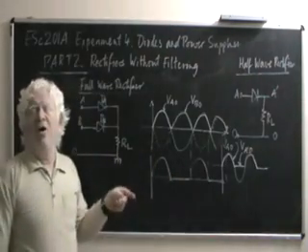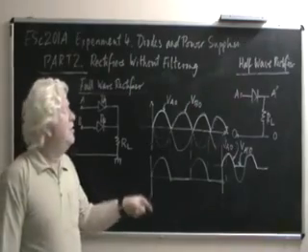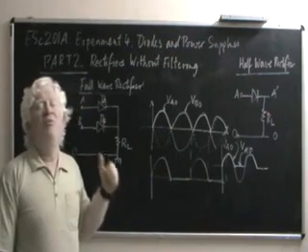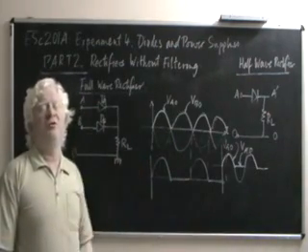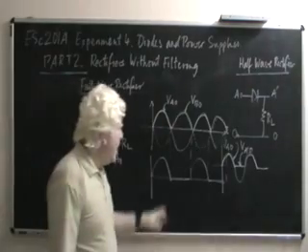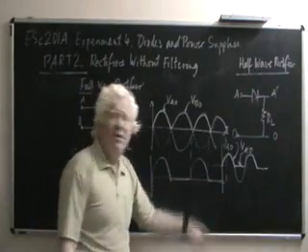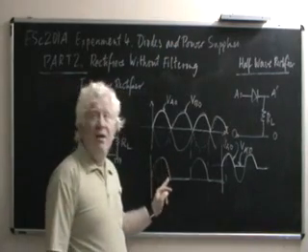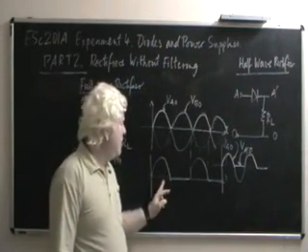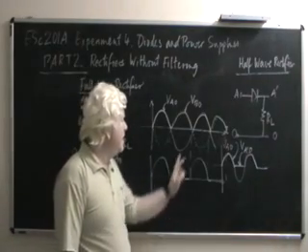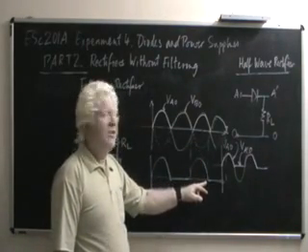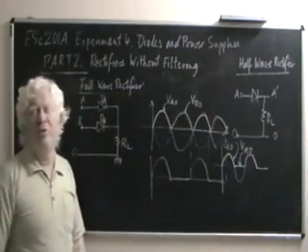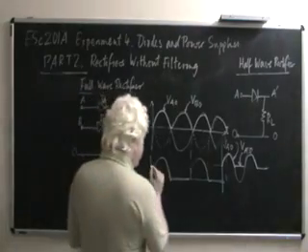We now speak of having achieved unidirectionality of the output voltage. We now speak of how to make this voltage as constant as possible. Clearly, the half wave rectifier looks extremely fickle. Sometimes it produces a large voltage which is along the lines of a sinusoid. At other times it is just zero. Again it's a half sinusoid, then again zero. Not at all what we would call a constant voltage. Ideally a constant voltage should be something like this.